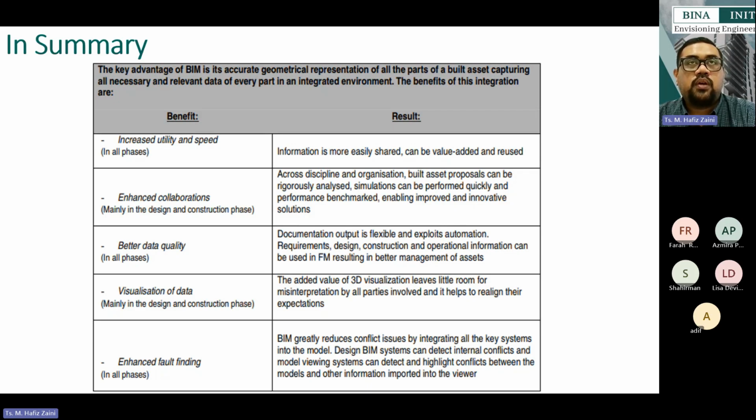Okay, so some projects are open BIM, which means not all of the stakeholders use Autodesk products. They are not all using Revit. For example, the architect might be using ArchiCAD, the C&S might be using Allplan or Tekla, and then the MEP might be using Revit. So from these three different roles, Revit can import and export the model to IFC for interoperability. That's the beauty of the Revit tools.